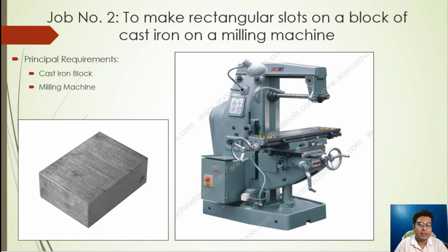Generally they are mixed with varying amounts of silicon and manganese and traces of impurities such as sulfur and phosphorus. It is made by reducing iron ore in a blast furnace. The liquid iron is cast or poured and hardened into crude ingots like pigs, and the pigs are subsequently remelted along with scrap and alloying elements in a cupola furnace and recast into molds for producing a variety of products.